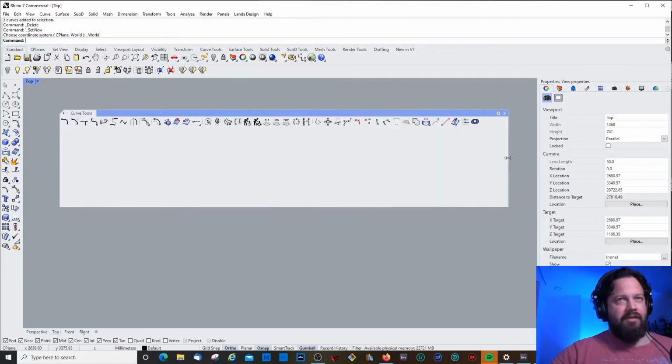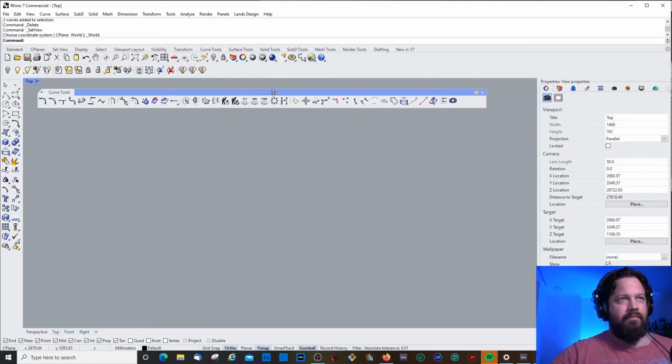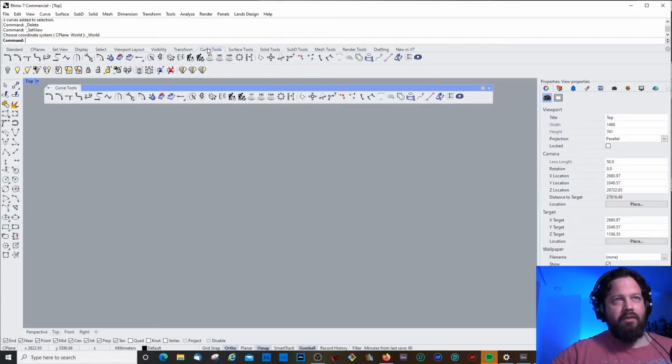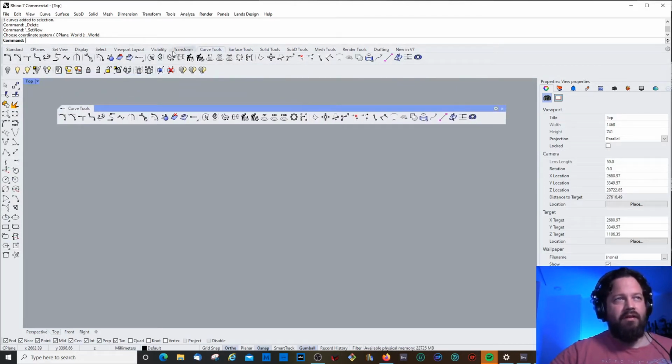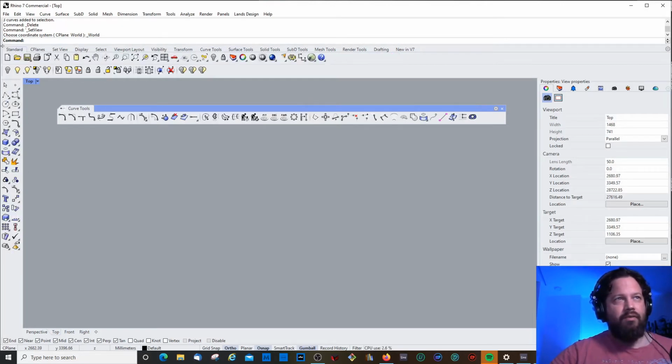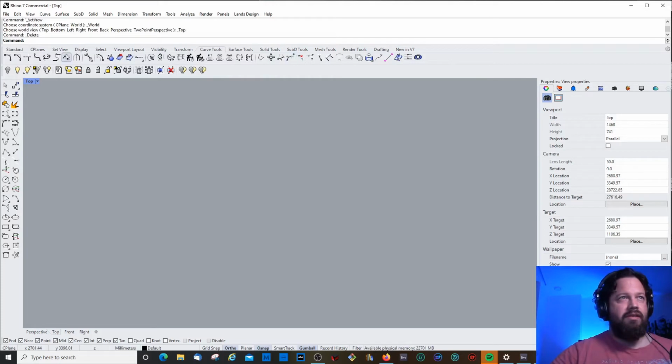Instead of having this tool open like that, we can actually also go in here. This is basically a copy of these tools. So you're either in the standard tools tool set or in the curve tools. And so we don't need this tool panel. We can actually use this here on the top, which is exactly the same. And then what it does, it adds here all the curve tools which we talked about in the previous videos. So all the curve tools to create curves are actually here on the side.